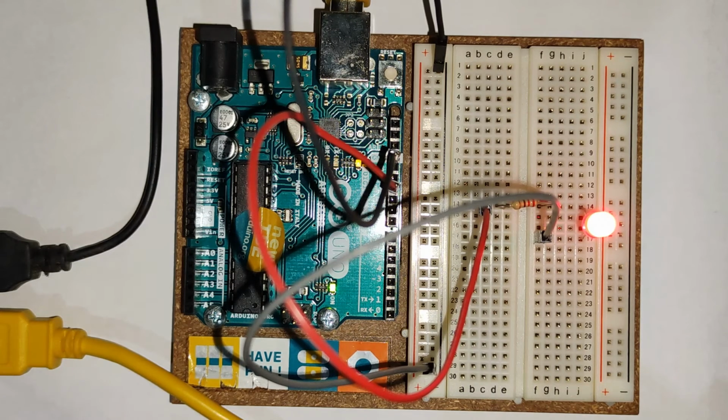That is the purpose of analog, right? It's like, for example, an LED, we have dimmest, dimmer, dim, then bright, brighter, brightest. It has a corresponding value. So that's the function of analog write. It doesn't only display two values, unlike digital write, which is high and low. Analog write displays different values and converts them to the corresponding voltage. So this one is a little bit slow, though it is already at 100 milliseconds.